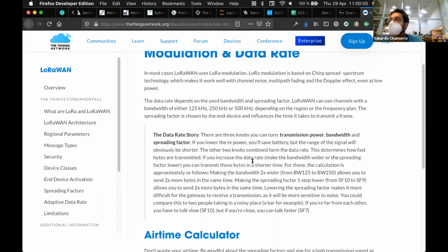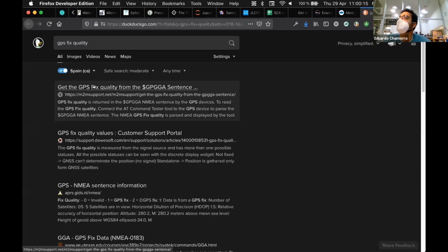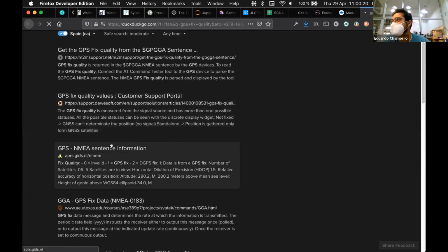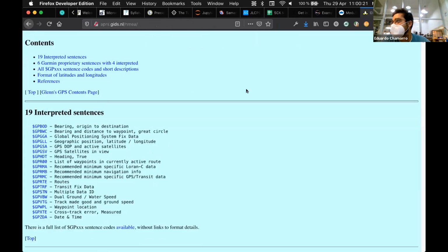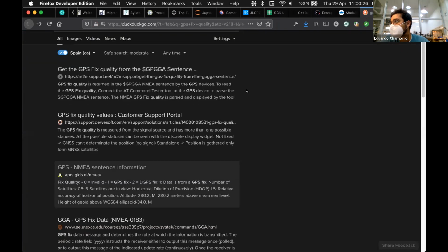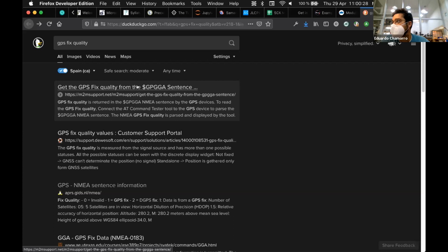But that depends on the part of the world. For example, in Spain we are under most of the GPS satellites, so it's really easy to get 16 or 14 locations in Spain. But I have seen in some parts of the world, for example in Siberia, it was impossible to acquire more than 5. So you never get what is called a GPS lock, which is actually locked in place, and you have at least one satellite of backup. That means you have 7 or 6.